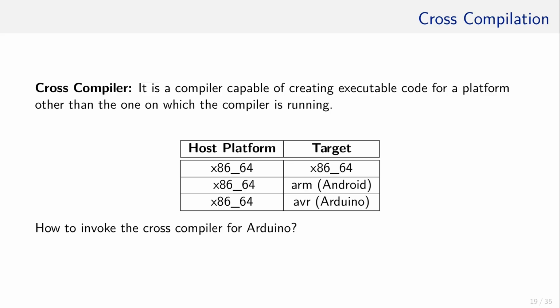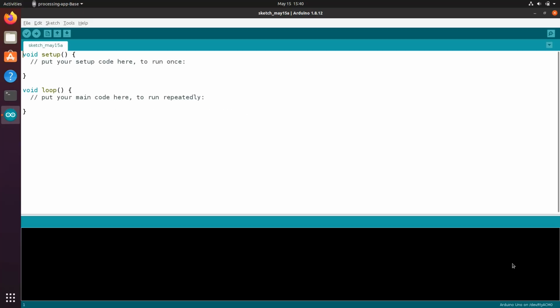We use the programs of the compiler collection, which is executed on your PC, to create programs for processors that are not in your PC and hence cannot be executed on your PC without an emulator translating all unknown instructions into the instructions your PC CPU understands. Fortunately, since we already installed the Arduino IDE, a cross-compiler is already available. We just have to find it.